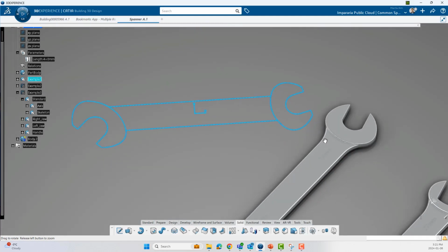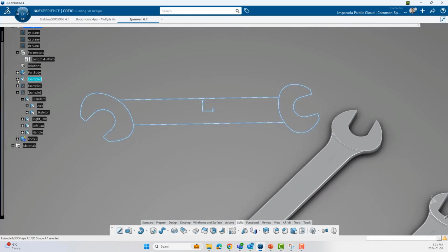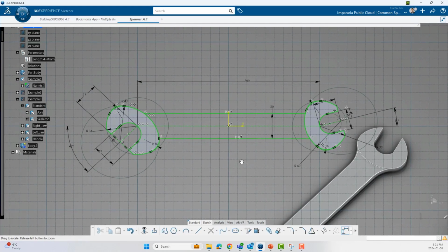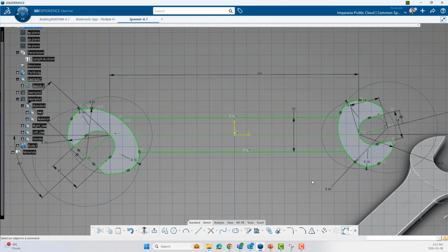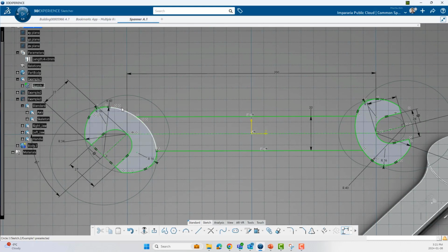Imagine that if you create the fillets from the start, it all becomes linked and hardly controlled. For example, maybe when you start learning CATIA, you might learn a sketch like this, where you create everything at once. This is only for practicing the sketch. But we don't want to create this complexity because it's very hard to modify. All the IDs might be missing later.